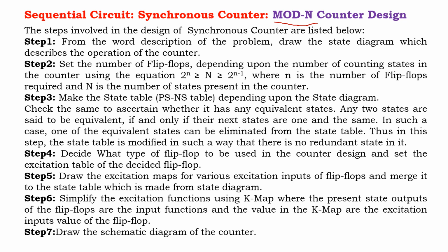The steps involved in the design of the synchronous counter are listed below. Step 1: from the word description of the problem, draw the state diagram which describes the operation of the counter. The counter will count from where to where, from which state to which state, and that will be defined in step 1. Then, depending upon the states, you should draw the state diagram.